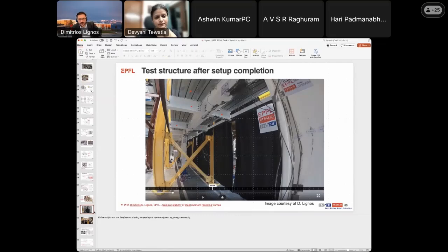In fact, the transverse beam, well, it depends on the configuration, but usually you will have a transverse beam. This is correct. The transverse beam, what will usually do is that it will increase a little bit the resistance of the joint. And you can, in fact, quantify this. This is something we are currently looking at.